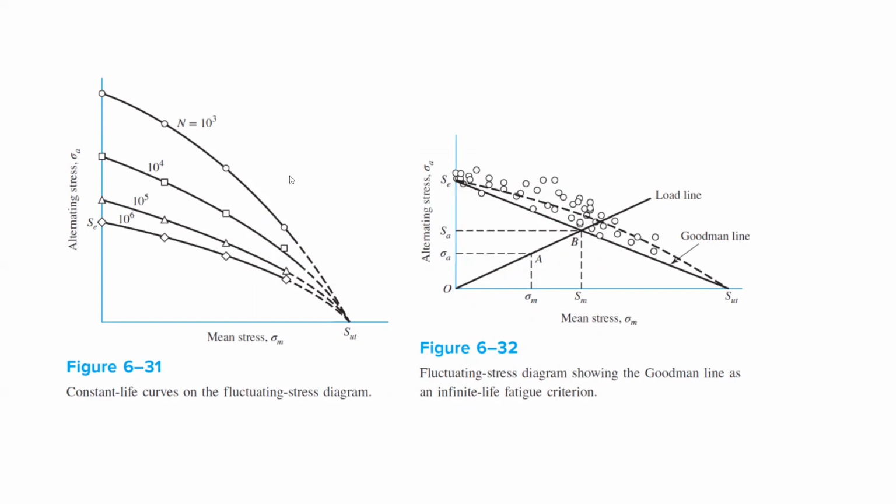It's called a mean stress alternating stress plot. The idea behind that is that you have two components typically of loading, some fair amount of mean stress. So let's say I take a rod and I just pull it a static amount of stress, and then an alternating stress. That's the reversing component on top of that mean stress. In combination of those two, you get different properties. And this plot is a little different, but these are basically isolines on the number of cycles.